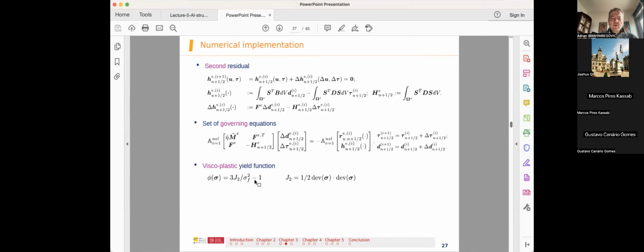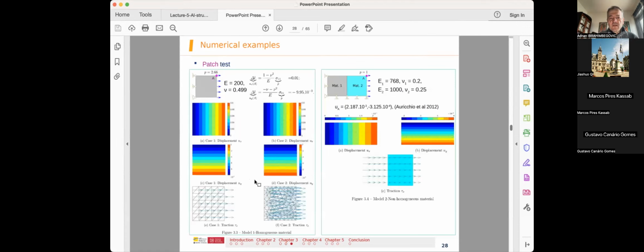If you want to have long-term computation, then we want to avoid using the operator split, which is imposed in classical plasticity. So basically, you can take a second order scheme and this type of conserving or decaying scheme applied and run it for a very long time. So this way, I can still use global computation when I'm computing my viscoplasticity, as opposed to being obliged to do it locally when I switch from viscoplasticity to plasticity.